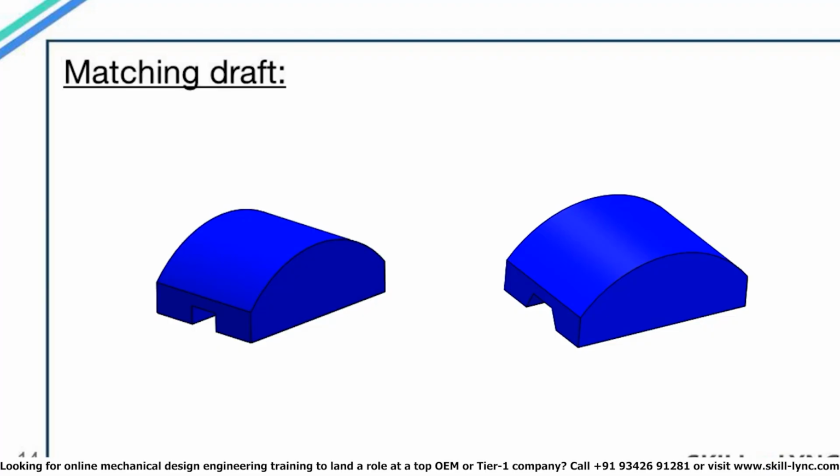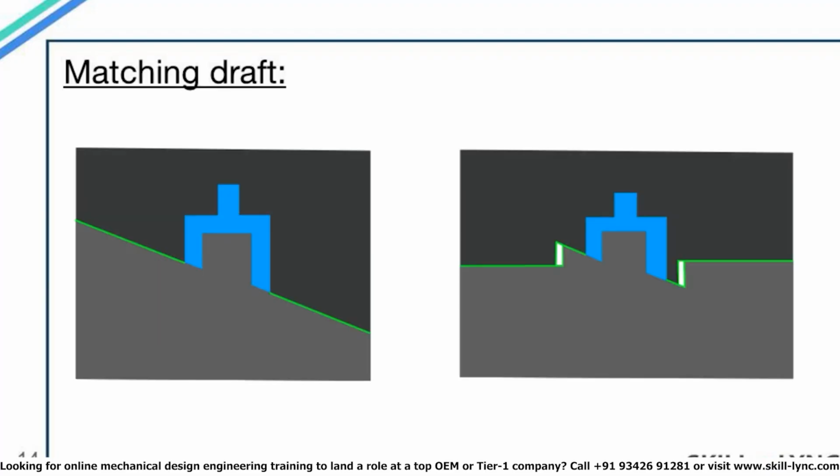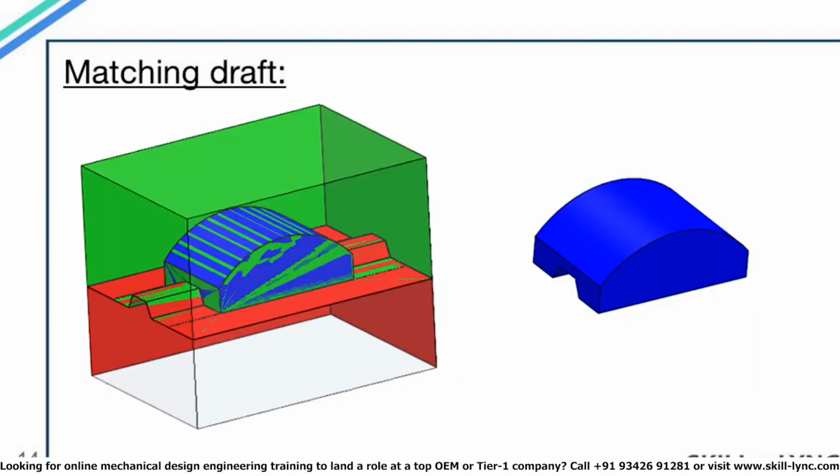Now there is another thing that I would like to explain here. While explaining the angled parting surface, I had mentioned that we don't follow the profile of the component throughout the entire mold block to ensure easier machining. Similarly, in this case too, we won't follow the groove profile throughout the mold block as you can see in the diagram here. The image may appear glitched, but it's not. It's directly taken from SolidWorks. This is how overlapping surfaces look in SolidWorks.